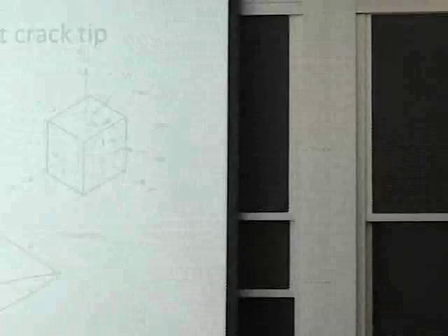Okay, so fracture mechanics, and that ties back to actually the last class. Professor Eager said at the tip of the crack you have a plane strain condition, which essentially means that you can't have flow through the thickness. So the thickness is the z-axis here. And therefore, you're building up that triaxial loading. And the triaxiality makes your flow stress go up.